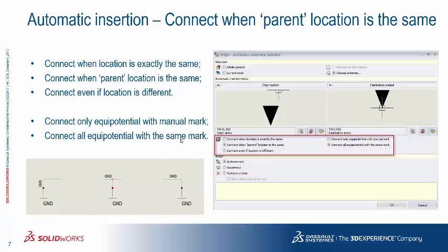This brings up another question from an old issue. When we do ANSI drawings with 11 by 17 split in half, up until now, 2016 service pack 3 is what we're currently on, it still doesn't treat the second half of the sheet as a separate entity. So when it goes ordering, it always goes across and then down, and you get order numbers split across the two sheets. So this is two questions in one. Has that been addressed, and if it has or hasn't been, how does that play with the new origin destination assignment? Does it go across the entire sheet, or does it go down the half and then down the next half?